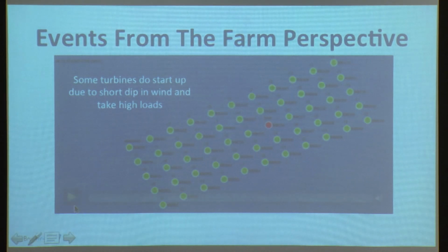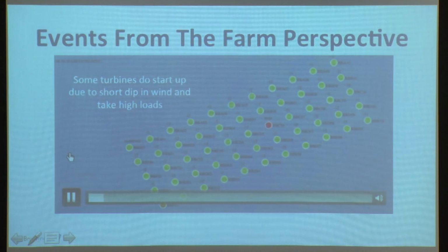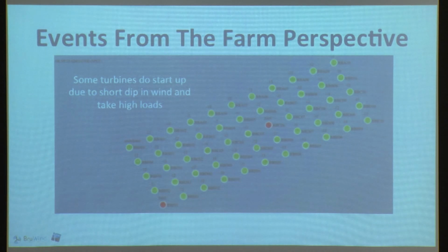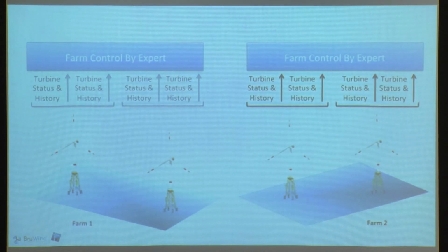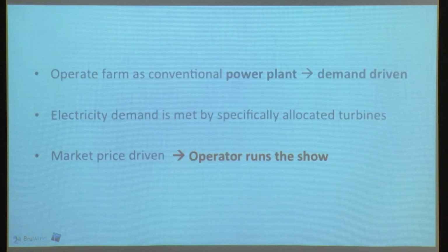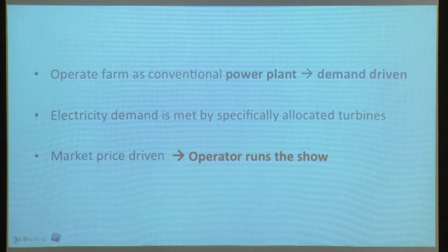So here you will see that they are all responding on their own, so you have certain of them starting up, shutting down again, and they do it based on their own information, which in the end, the majority would suggest not to start up and produce energy. Most of them produce energy for 10, 15 minutes, which in the end doesn't bring too much money, but costs quite a lot of lifetime. And if you are able to do this, the next step then is, if you have the load history, you have the condition of each turbine, you can start using offshore as a conventional power plant.